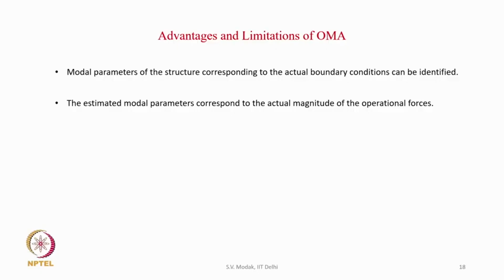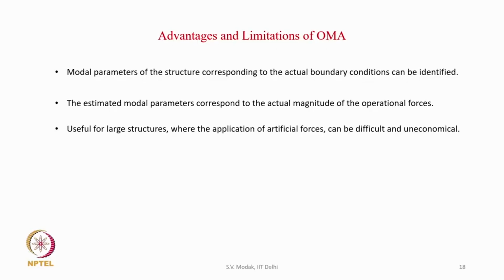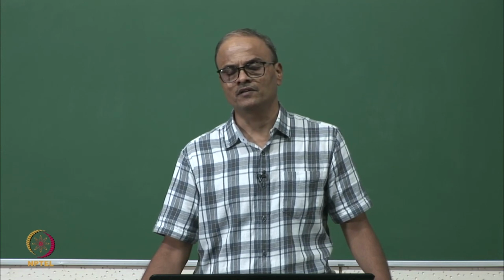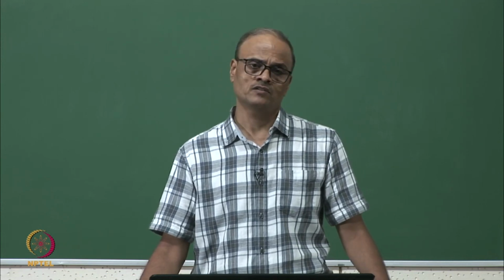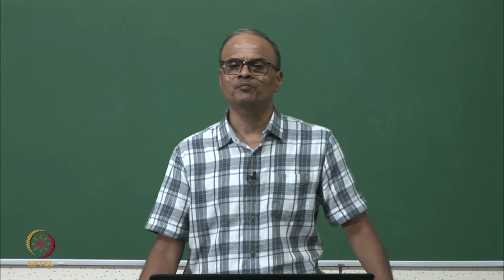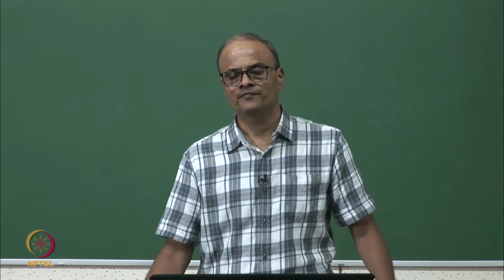Another advantage of the operational analysis is that the estimated modal parameters correspond to the actual magnitude of the operational forces. Operational analysis is also useful for large structures, right, where the application of artificial forces can be difficult and uneconomical. One limitation of OMA is that the estimated mode shapes are unscaled, but in EMA we get scaled mass normalized mode shapes. Also, operational analysis requires the presence of some white noise excitation. So, in cases where white noise excitation is not present, operational analysis cannot be used.